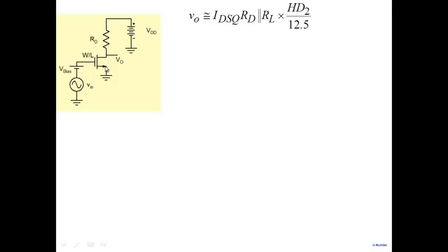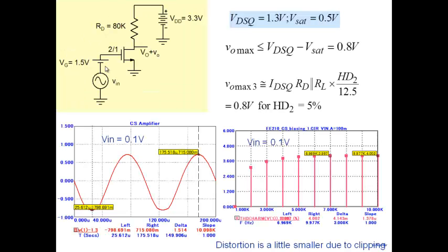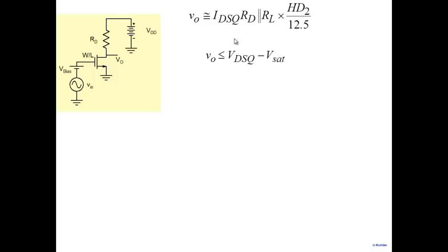maximum swing? Okay, so here in this case, we had already given you a design and we were asking you what is the maximum swing that you will get. So all you need to do is plug in all the values, find out all the limits here, find out whichever one is smaller, and that's the output voltage swing here. But if you're given a design question as to how do you design it so that you get maximum voltage swing, then one proceeds as follows.